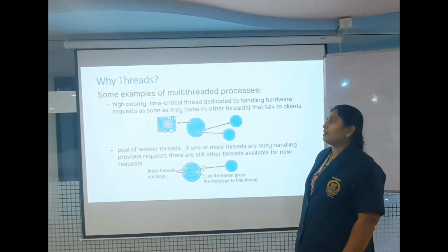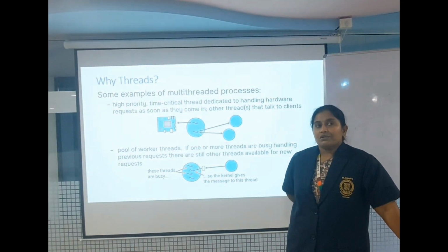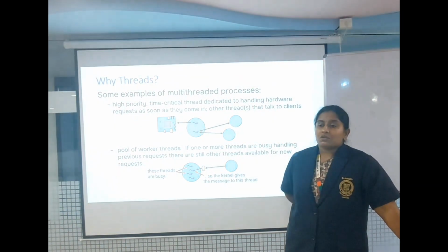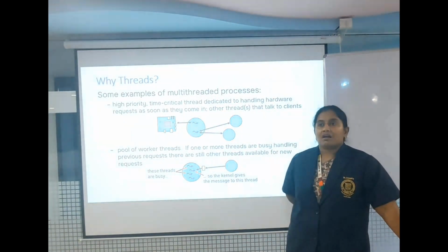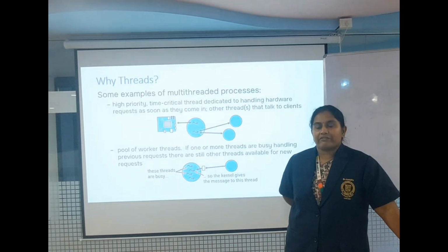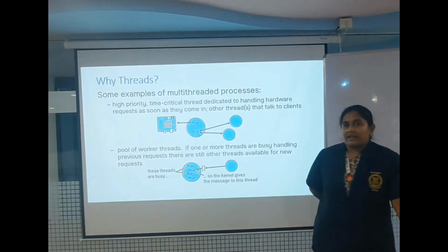This comes in handy, because embedded systems today mostly run on multi-core machines. So you know that there are several cores present from the hardware perspective. What these threads can do is use the multiple cores. There is something called core affinity, where depending upon the nature of the task, a core is allocated to the thread. These are some advantages of having multiple threads in the QNX system.